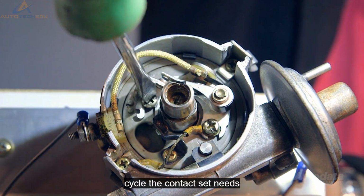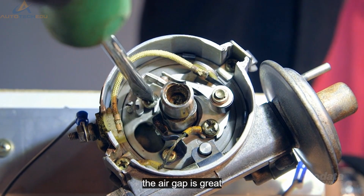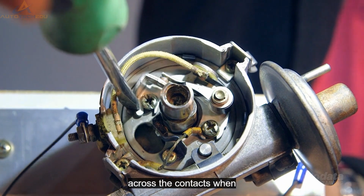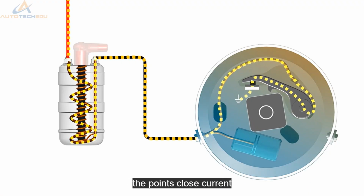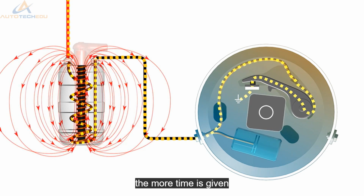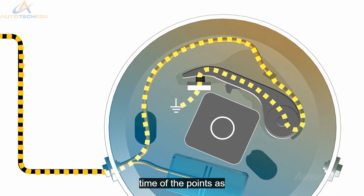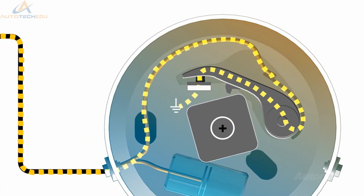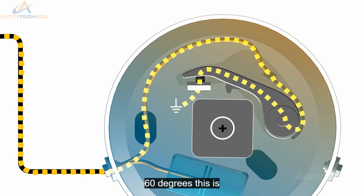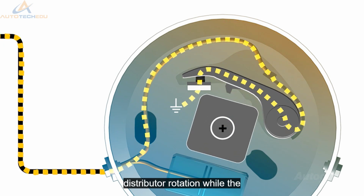The contact set needs to be adjusted to a minimum clearance. This ensures the air gap is great enough to inhibit current flow across the contacts. When the points close, current again passes through. The longer the points are closed, the more time is given to coil saturation. We refer to the close time of the points as the dwell angle. The dwell angle for a 4-cylinder is typically about 60 degrees. This is the number of degrees of distributor rotation while the contacts are closed.